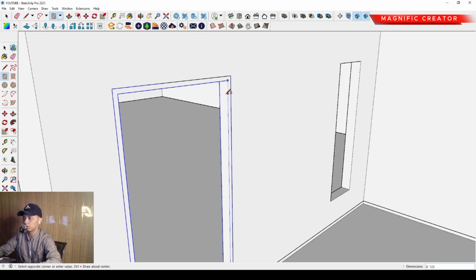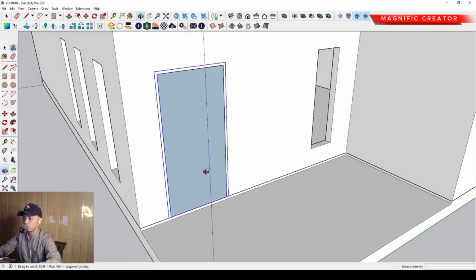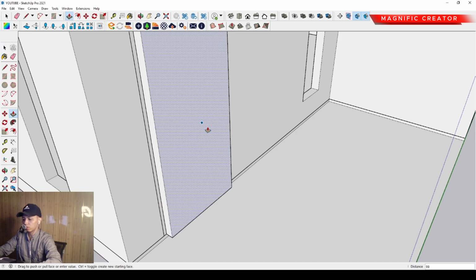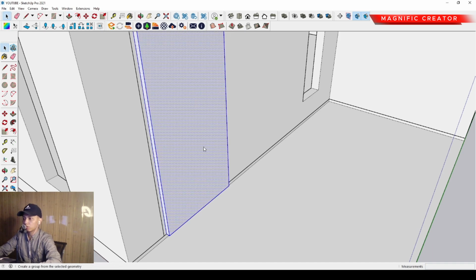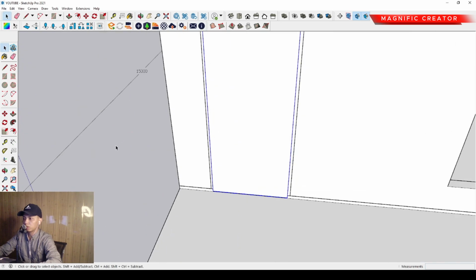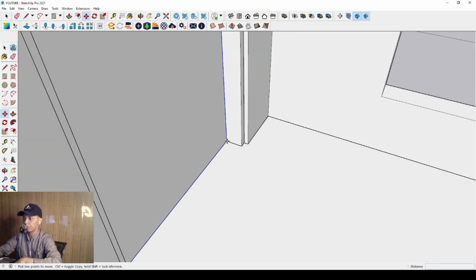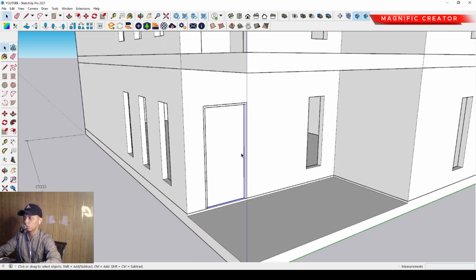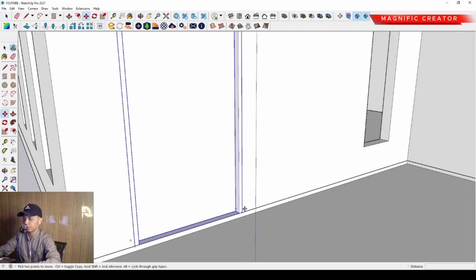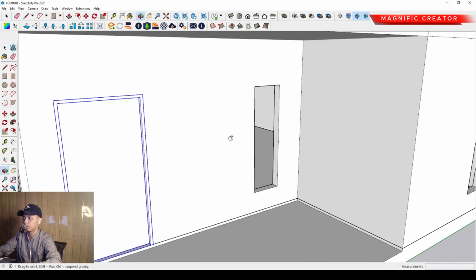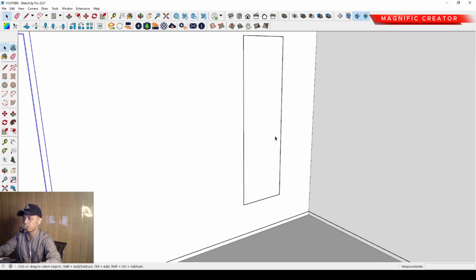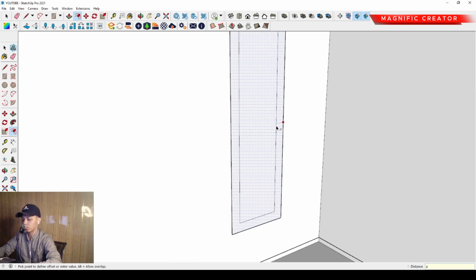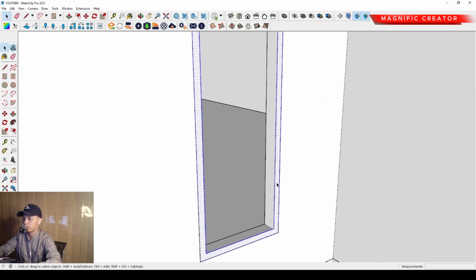So then we can make the wide size of this door panel. We can set the thickness around 50 millimeter. And don't forget to make it a group for easy modification in the further time if we would need the modification. Okay, so then we can make the window frame near rectangle and offset it inside with the offset tool around 40 millimeter, and just erase. We can push it to the back around 120 millimeter and make group. And of course we can make component create.